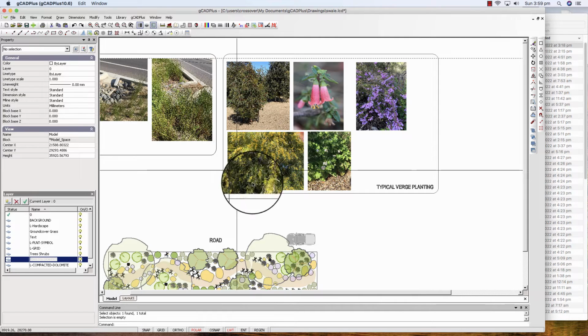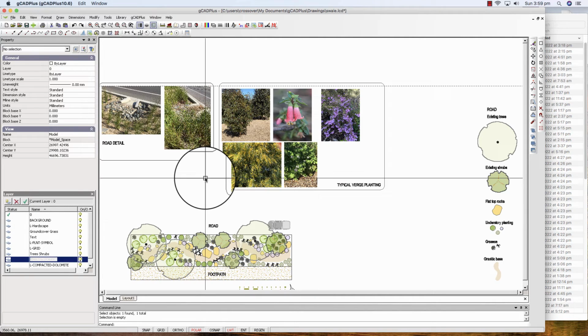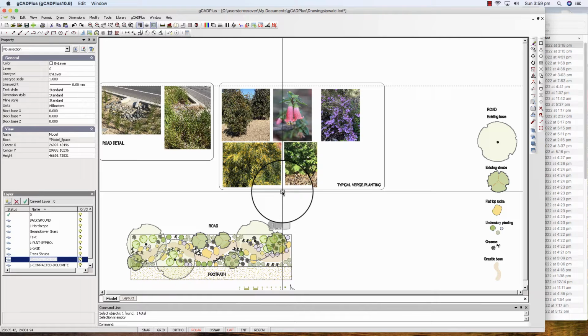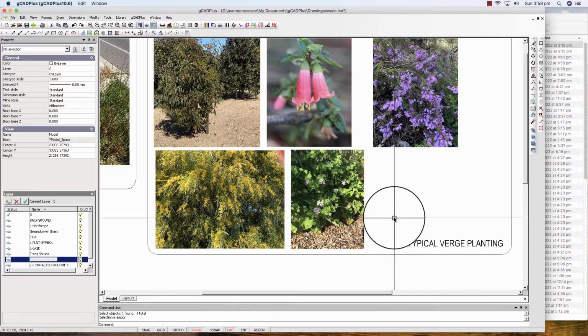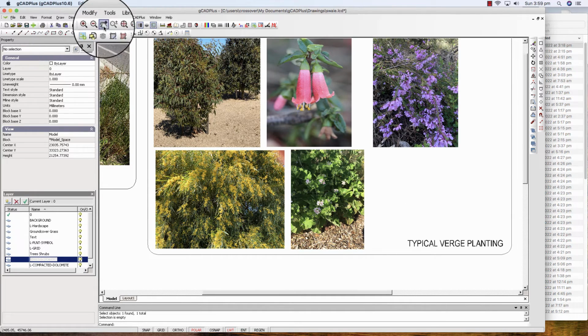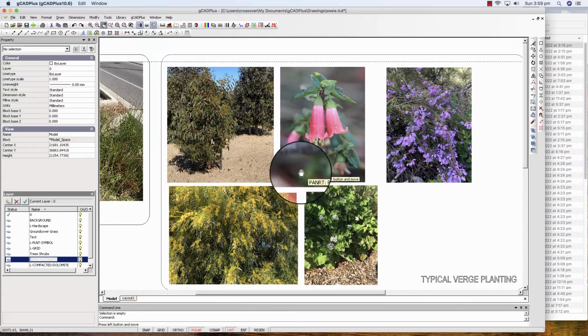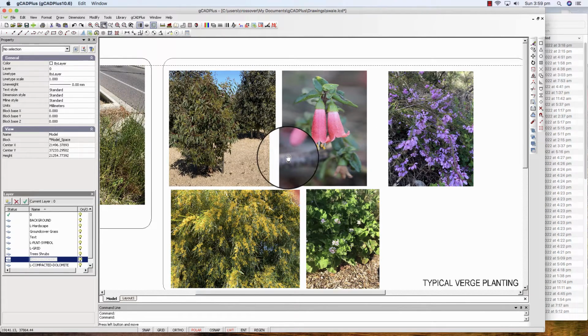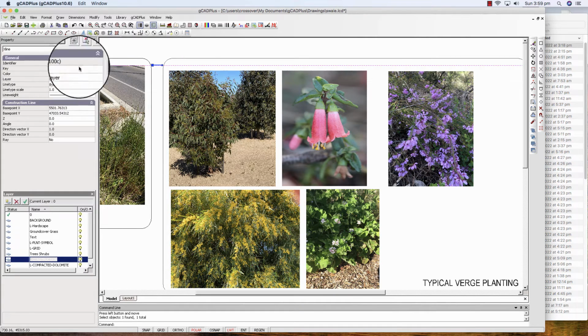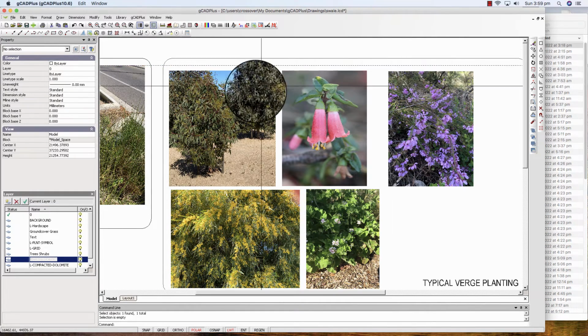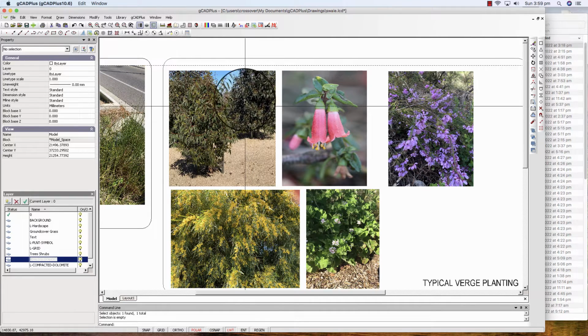And what I want to show you here is that you can use the same object snap tools that we've been using in the draw environment when you're handling images. So an image just lives in a frame. I need to pan down like so. So what I've done is I've put a construction line across here, an X line runs across. So I want these images here to line up with that construction line.